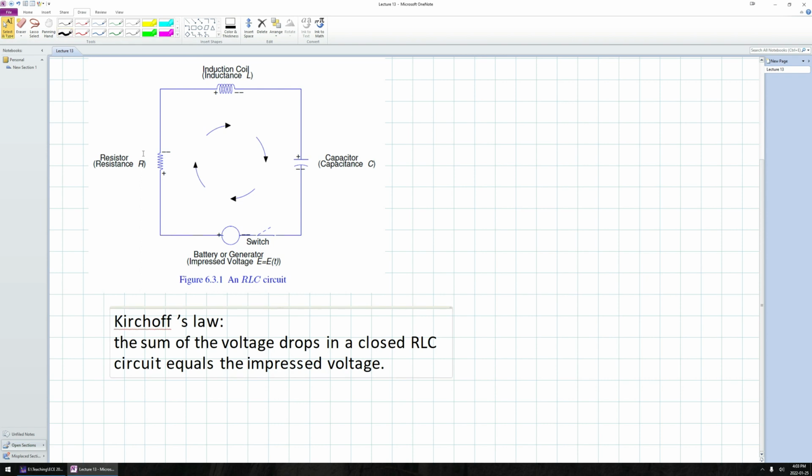Okay, so let's chase out these details by figuring out what happens with each one of these elements of the circuit. What is the voltage drop when I go past the resistor? Well, in order to talk about the voltage drop across the resistor, I need to introduce the idea of the current. The current is just the flow that's going across here. So I define this thing I, and I represents the current as I go across here. With this new variable I, we know from Math 115 that the voltage drop due to this resistor is simply equal to the resistance of the resistor R, which is generally given to us in ohms, multiplied by the current, which is generally given to us in amperes. So here we simply get V_R is R times I.